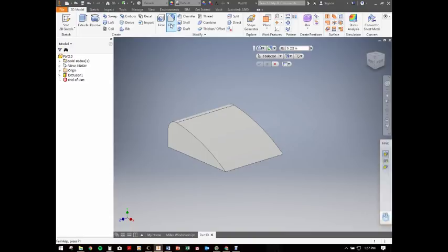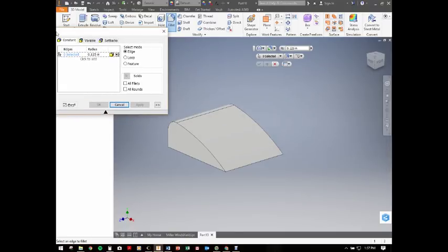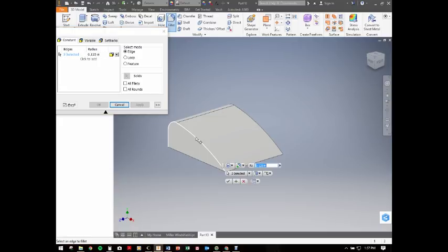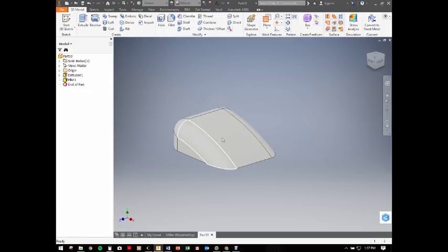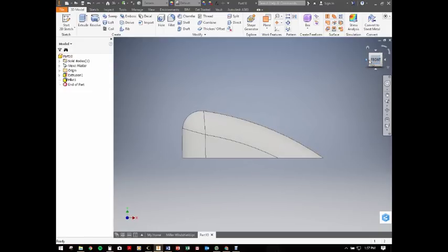This is where the fillet is. This is where, if you didn't do this right, you're going to see it. All right, if you didn't add those tangent constraints, it won't let you select this arc as a whole piece. I need to put a 0.5 there for the radius, and I need to do the same thing on this other side here, and we're okay. So there we go, we're halfway done. There's the first part of this shape.